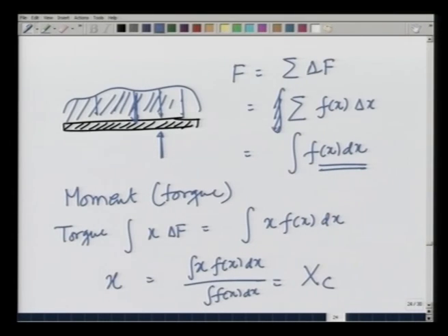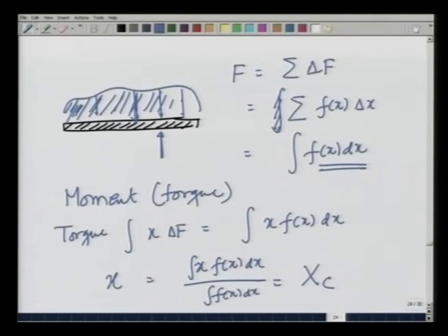So, we can say that effectively the force acts at the centroid of this given area which describes the force distribution. So, you see immediately the connection between the first moment or the centroid that we define with a problem in mechanics.